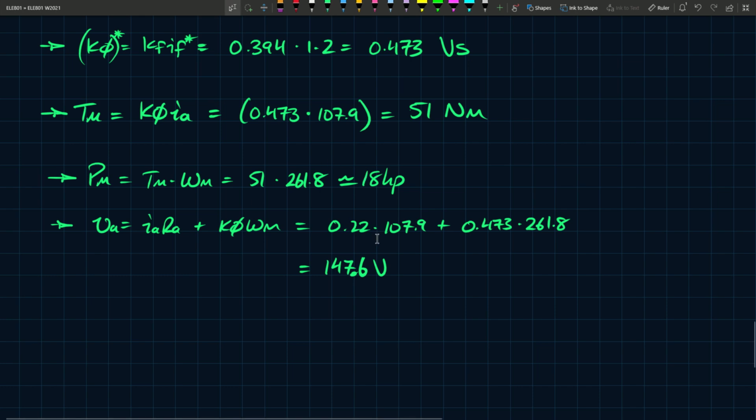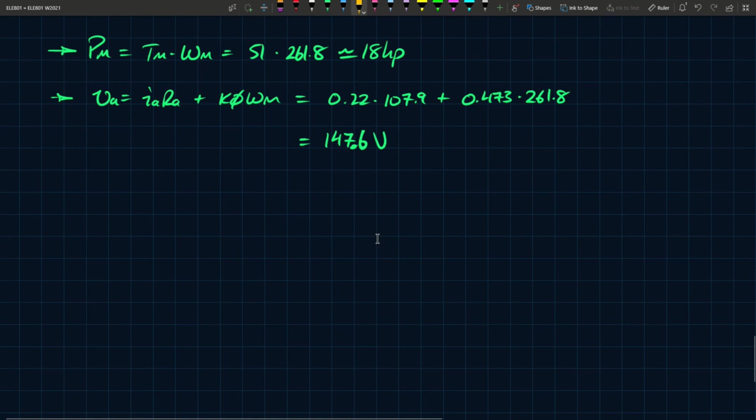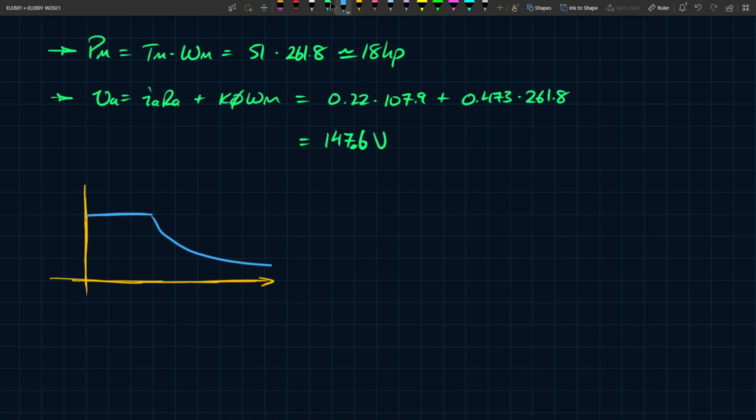Now, one thing we can try to look at, to better visualize what is happening, is our characteristic. Let's look at this characteristic that we're so familiar with at this point, and I'm only concerned with the torque. The torque will look something like this. This is Tm, this is omega m. And here we have the base, and the base we said for this question was 157.1, and this maximum torque reference that we gave here was 85, right?